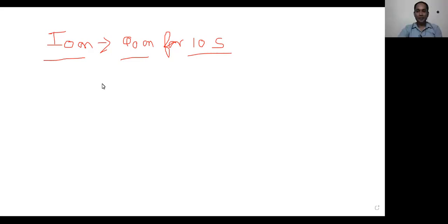So I told you that if we follow a few steps, it's 10:26, I shall move fast. If you have to make such a program, we can follow a few steps. What are the important things you have to remember? First thing, again I shall tell you: to switch on, NO, and to switch off, NC. Very first common thing we have to remember. Second thing, whenever we get a start signal, we need to latch that with some flag first.